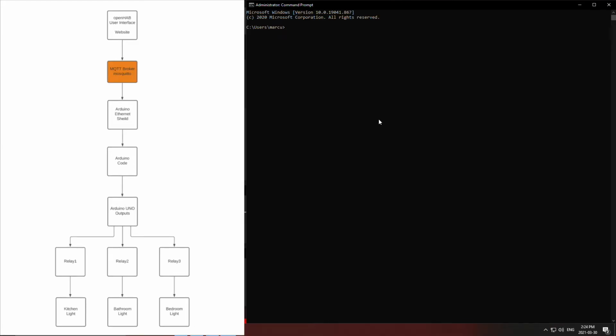Next on the block diagram is the MQTT broker, which acts as the middleman between the technology and physical components of the project. A broker is another word for a server that continuously looks for signal inputs from openHAB and then sends that signal to our Arduino Uno to be interpreted. The version of the MQTT broker that is being used is one called Eclipse Mosquitto, also supported on Windows, Mac, and Linux. Through my experience of implementing the program into the project, it was rather user-friendly.